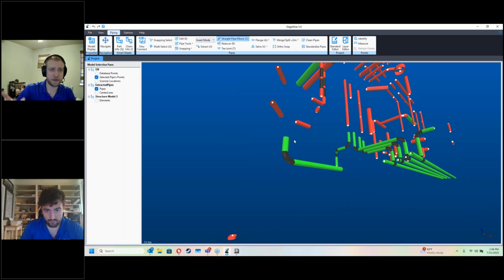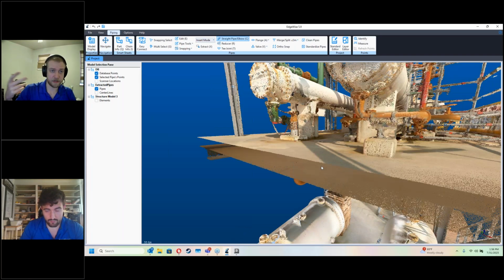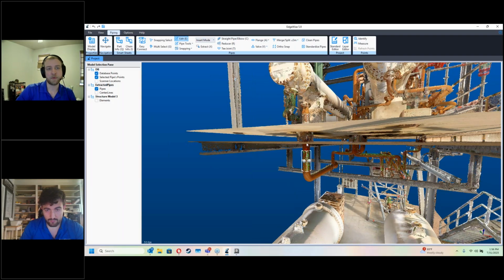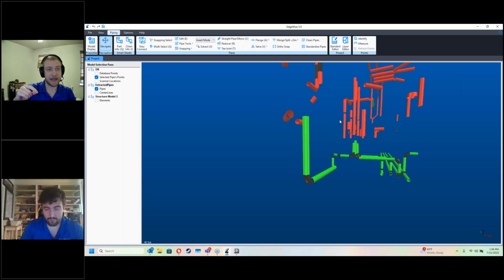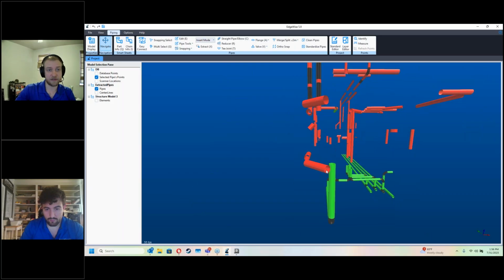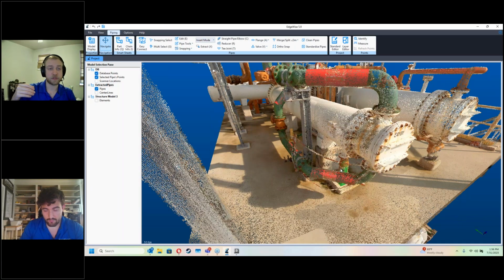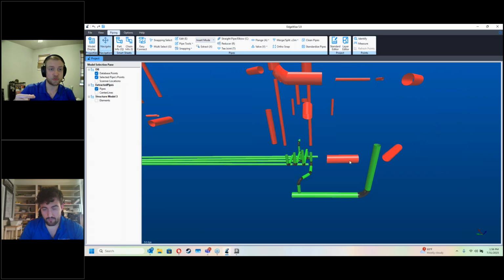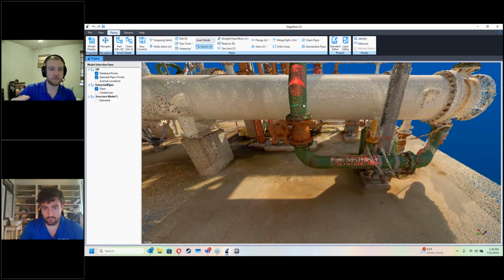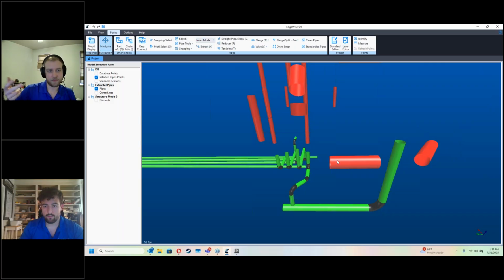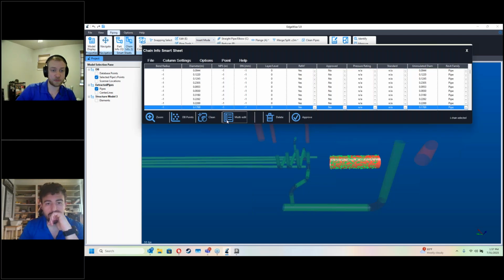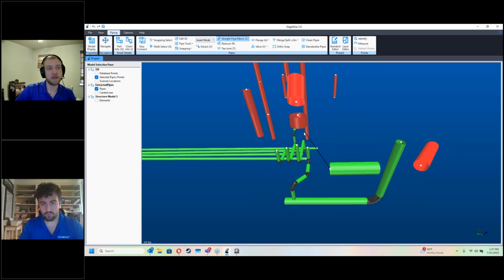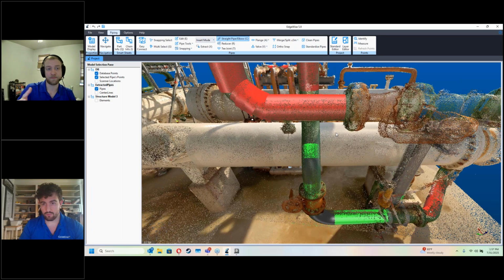What we do is look at the spec diameter that you select. So you say you want to use ASME or a custom spec. We're going to bump the actual diameter of the pipe inside of EdgeWise up or down, whichever is closer to an actual diameter in the spec. So if we're close to the actual diameter of a nominal 200 millimeter pipe, we're going to bump it to that nominal 200 millimeter pipe's actual diameter.